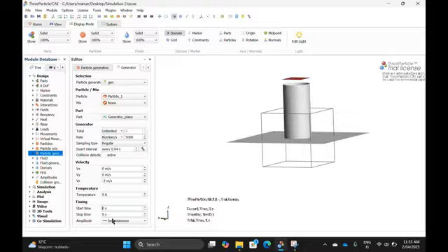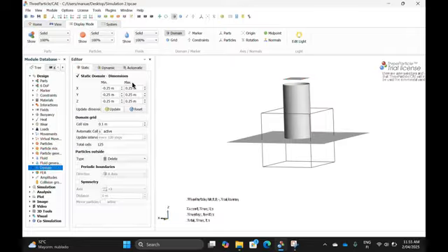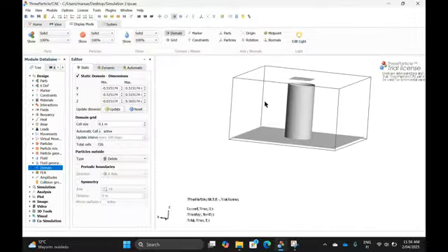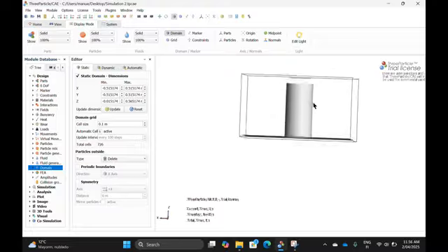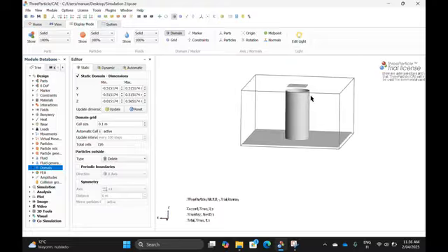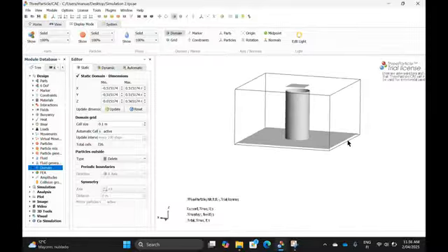One major thing, our domain. If you look at that, it's not working because our particles are generated here and would be deleted instantly. In the last simulation we didn't address it because we stayed inside of our domain. Now we need to adjust that a little. Here you can change the size of your domain. A good starting point would be automatically update and try to fit everything around the particles, the boxes, except that one that is set to no collision. So you need to adjust that a little, a little bit higher, something like that, and you're good. Doesn't look so bad, right? Everything is inside, looks good so far.